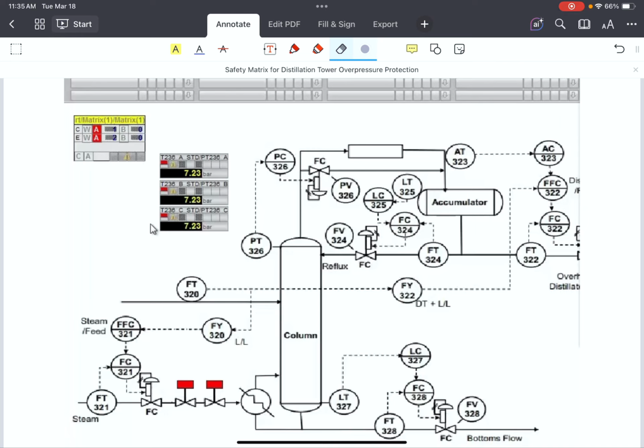So when we restart the CPU, we decided that these valves shouldn't operate automatically in case of a power cycle. We decided on operator acknowledgement to energize those valves, and the control is performing like before.